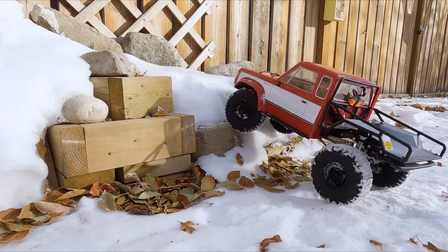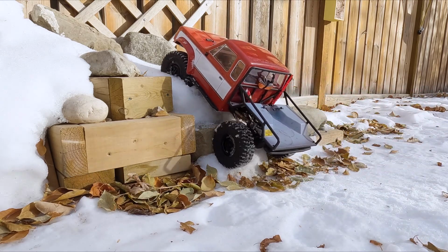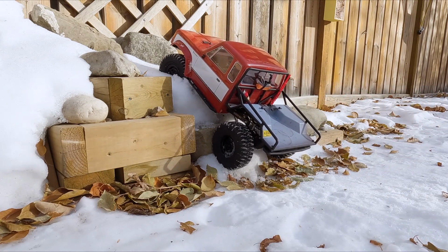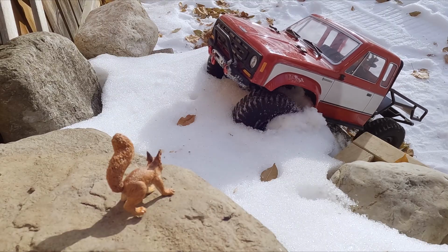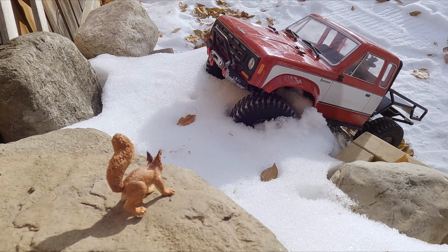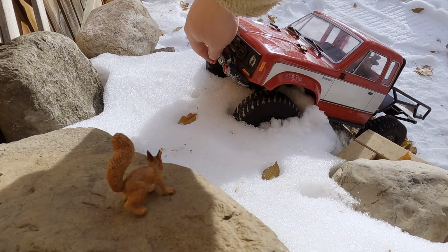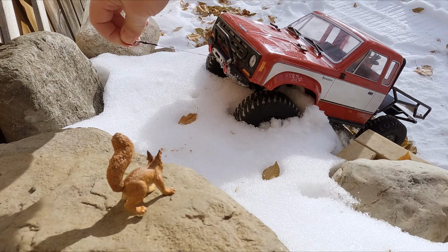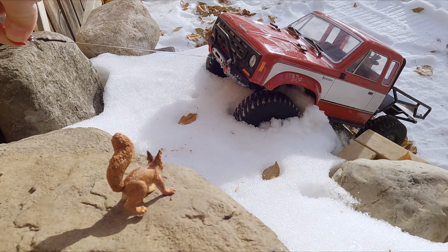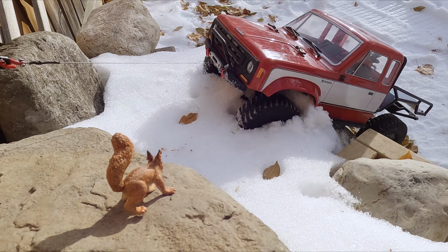Isn't that cool? You now have a very versatile winch setup. You can winch as you always have, for example, to pull a friend's truck out of a mud hole, or you can activate mixing and synchronize the winch and throttle, just like those PTO winches we see in full-scale off-road challenge competitions. With both throttle priority and winch priority channel mixing, the tire and winch movements are synchronized.